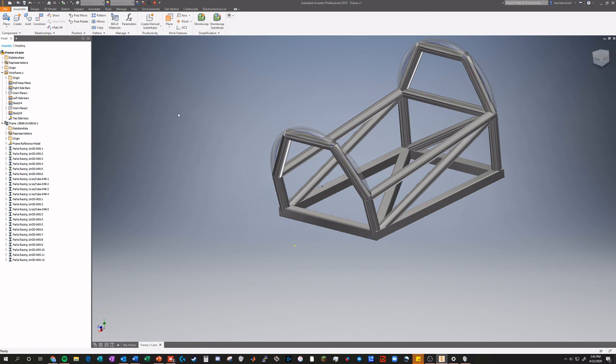So that being said, that leaves you with a couple advantages and disadvantages. The big advantage is that you're going to be a lot less likely to have meshing issues, and the meshing issues that you do have are usually easier to fix and happen faster because it's not a super fine mesh.